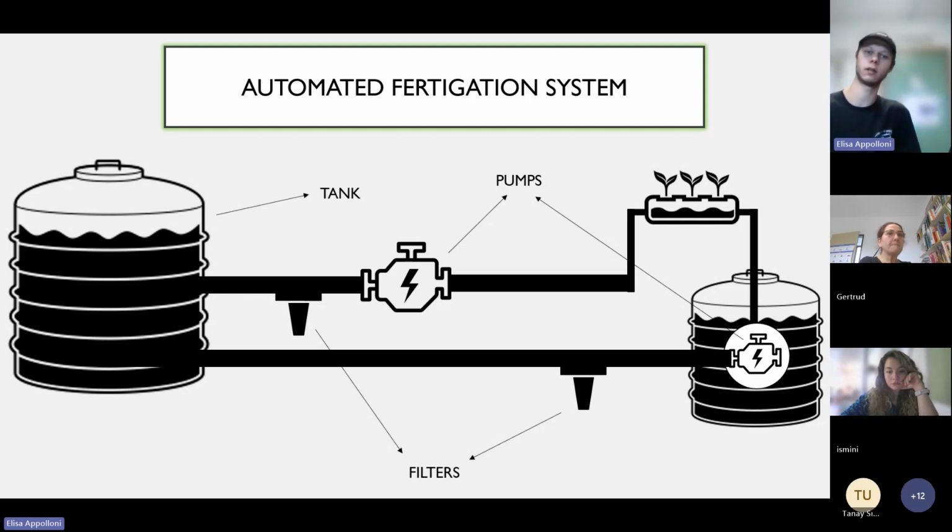But there is also a filter before the pump because it's very important for the maintenance and the management of the pump, to avoid that any particle can damage the pump. And so the use of a filter is fundamental in order to avoid the need of replacing the pump once a year because it breaks due to the absence of filters.